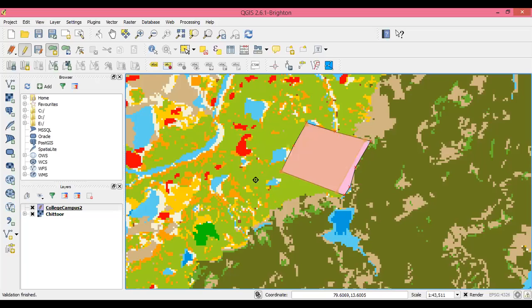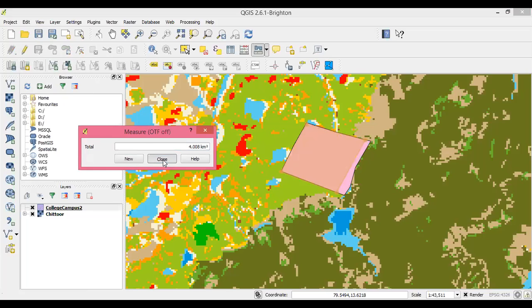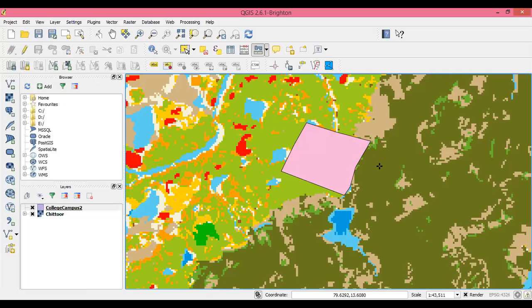This is the boundary of my college campus. Okay. So now you want to save this. You can just click save over here, save layer edits. So it has saved it. I'll stop editing. Okay. So this is my college campus boundary that I have created. So it's all very straightforward, nothing sophisticated. You just click, you create a polygon.